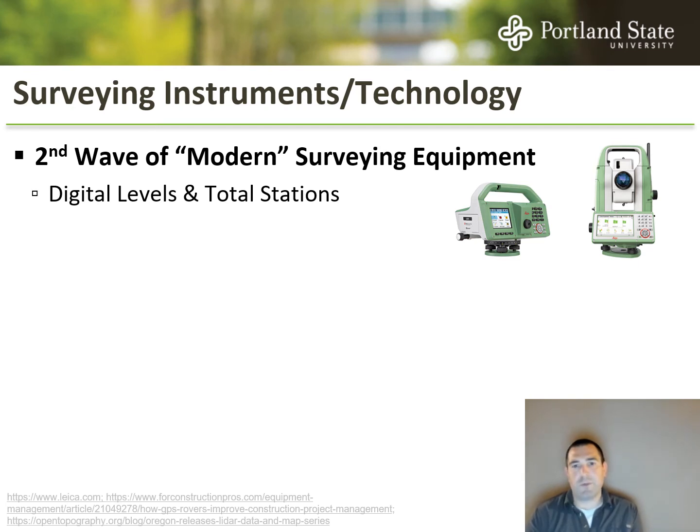Whereas a lot of survey crews in the past have been two people, nowadays with robotics, either robotics with GPS where you only need one person, or robotics and a total station that will automatically move and follow you when you have this prism that's reflecting this laser or this microwave radiation back to the total station. That's the way that we measure distance nowadays as well. It gets pretty interesting.